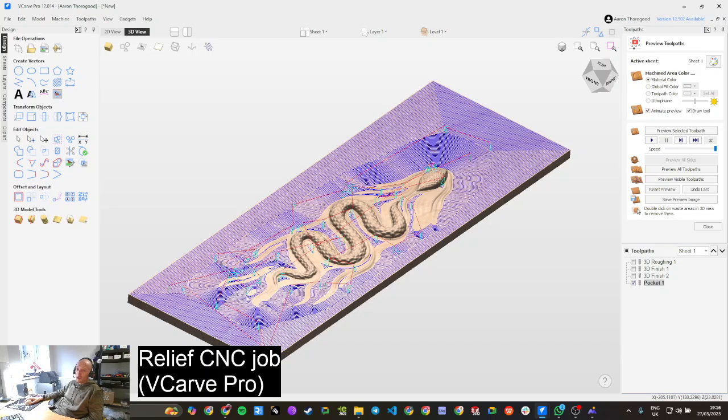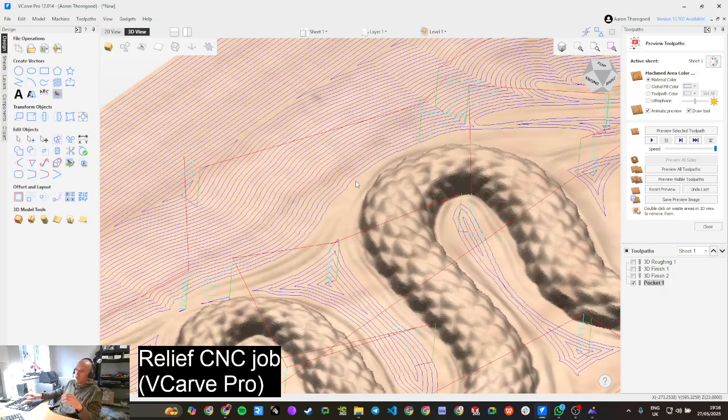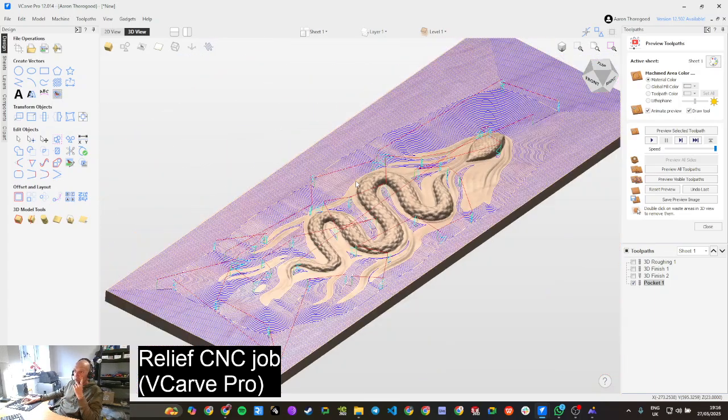Oh, the one thing that I should have been a lot more diligent on is when I was probing between tool changes. As you can imagine, the depth accuracy when all those 3D contouring things blend with the flat sections, if there's any error between the Z zeros when probing, then you're into a lot more sanding.